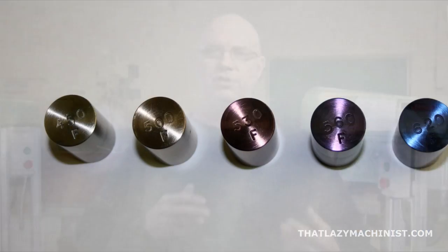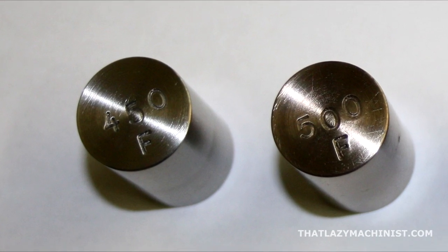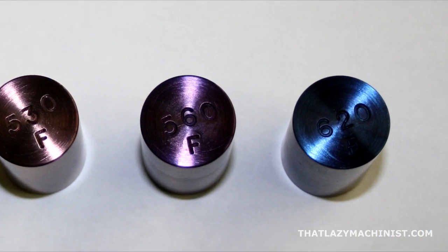Now, there's probably some of you who are wondering by now, how am I going to measure the temperature of the chips that I'm producing? Well, you don't need to measure the temperature. You need to observe the temperature. In our video about heat treatment of steels, we saw that the color of steel changes depending on its temperature. For high-speed steel tools cutting into steel, we want a very light yellow or no discoloration whatsoever. However, if you're using carbide tools to cut steel, you're going to want a nice light or dark blue color.